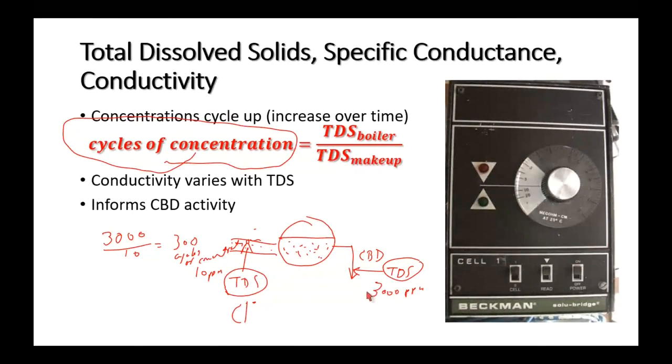then that's non-scale forming, it's not alkaline, it's kind of neutral in terms of what it does. We could get chloride stress corrosion cracking, but that really only happens in stainless steel. It's not a big factor in carbon steel. So really, these chloride ions have a neutral effect on the boiler water.